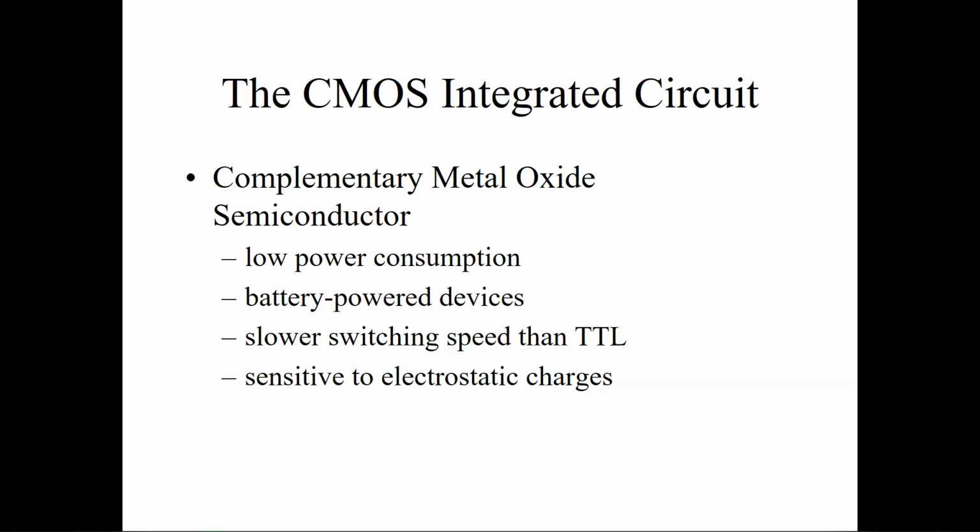Okay, so it's the same. I didn't know if it had to be dealt with differently than regular computer parts, but essentially it's the same thing. You just clip to something metal. Yes, while you're wearing that band. Yes, because if you don't connect to something metal or something that'll help pull charges off, you can build up enough of a charge that it'll pop from you to it and fry your whole circuit. That's how delicate some of these can be.